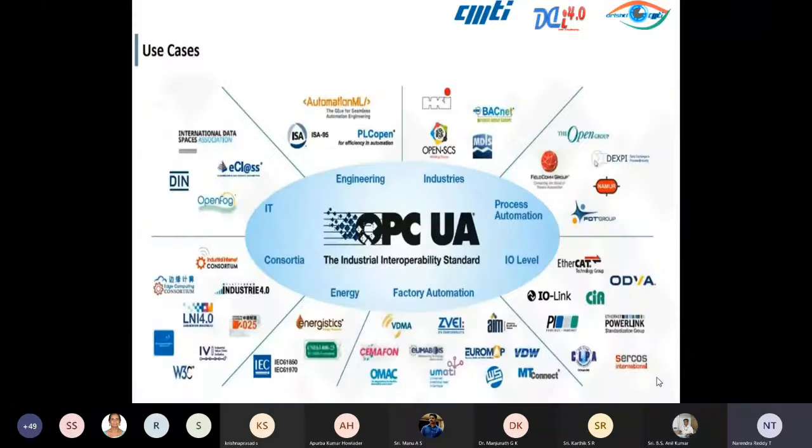Wherever you are, you can see here, this is related to energy. Those people are also accepting OPC UA. And this is some food processing industries, like process automation. Those people also have to give OPC UA so that you can make your own customized solutions for your factory. The embedded hardware is already there in the machines. You need to tell them to give data in this format only, OPC UA data format. It has become an interoperability standard. You need not worry about what kind of interface they are providing. You just worry about the format, the way the data is coming.